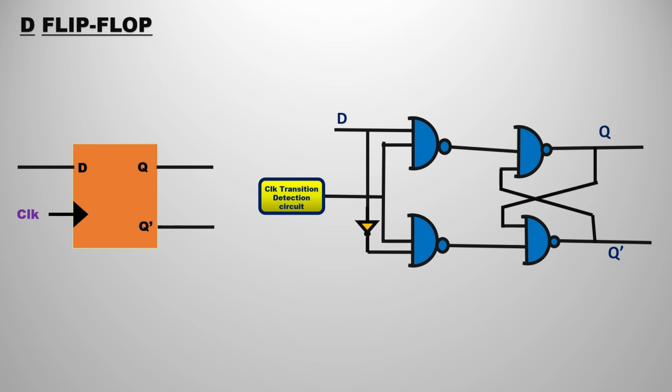Now we are going to construct the D flip flop. It is exactly the same thing with a little change from the SR flip flop. Combine both SR inputs and join a NOT gate for the R input, so it becomes like that. You are only sending D, and D bar to the R input. Everything else remains the same. This is the D flip flop. Now we are going to apply the preset and clear to this D flip flop and verify the circuit.